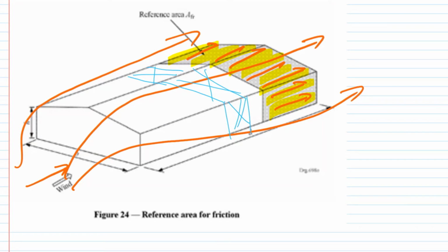Okay, so that's taken us through this session where we've gone from how do we take our building and find a pressure acting in the area of it, depending on where it's built in the country, how high above sea level it is, and accounting for terrain roughness and those sorts of factors.